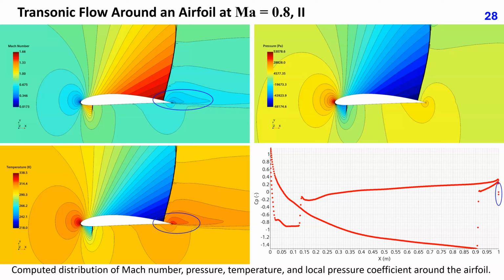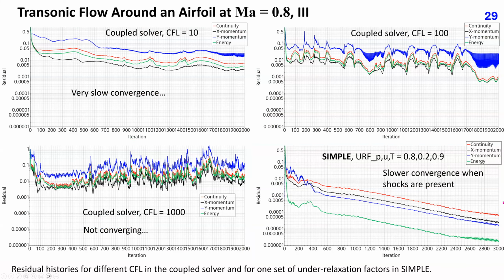At the far field around the airfoil, pressure is everywhere the same, equal to the atmospheric pressure. Also, pressure at the trailing edge must be the same when approached from the suction side and from the pressure side. This shock is needed to raise the pressure to the level required by the downstream condition.